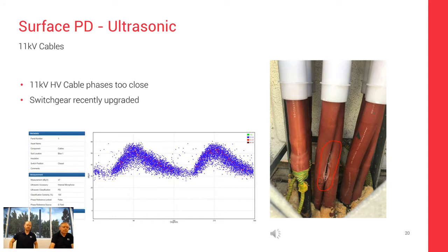So here is another real-life example. This one here was on the side of the road at a ring main unit in Australia. We can visually see PD occurring between the 2 phases, where you can see that white discharge occurring. There's high electrical stress points there, and there's defects in between those 2 phases where there's too much electrical stress, it can't hold in the volts, and PD activity is occurring. It may also be affected by contamination within the box, such as dust and debris and all that sort of stuff. High humidity as well within the box, maybe speeding up the process.